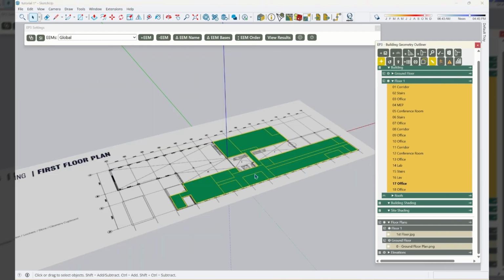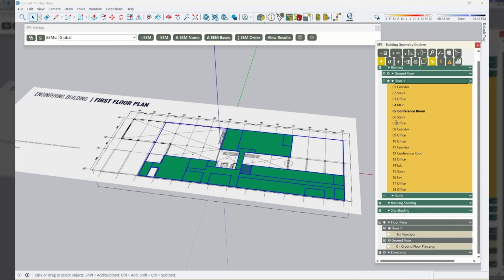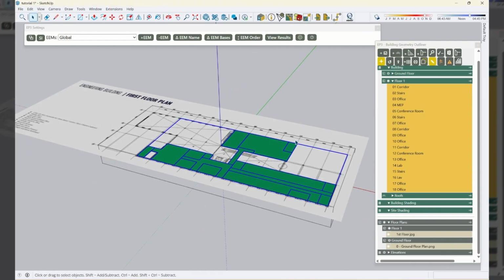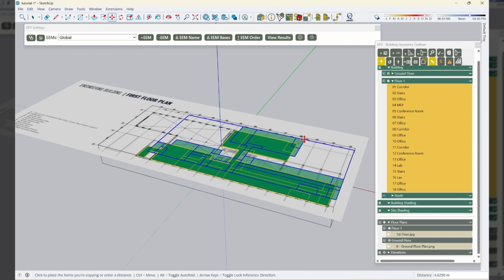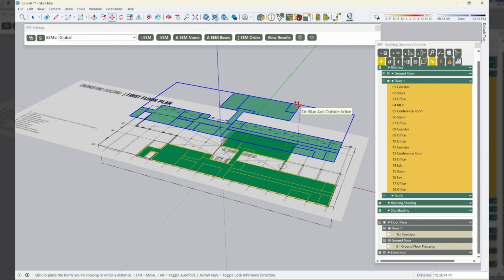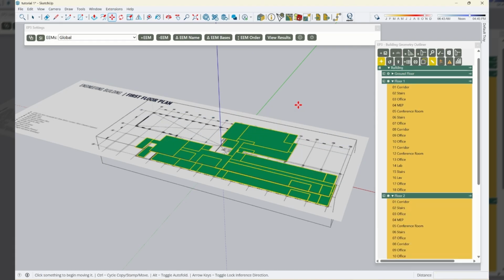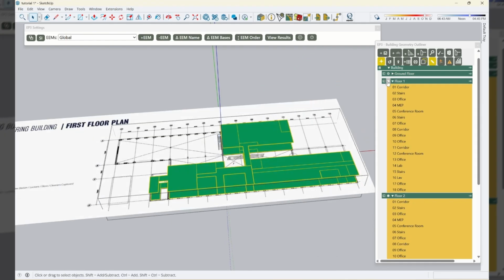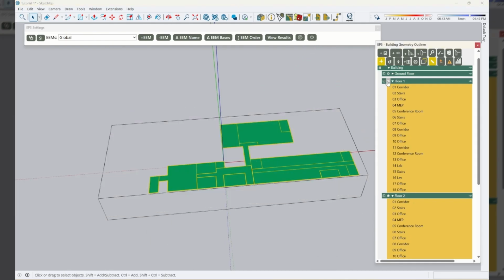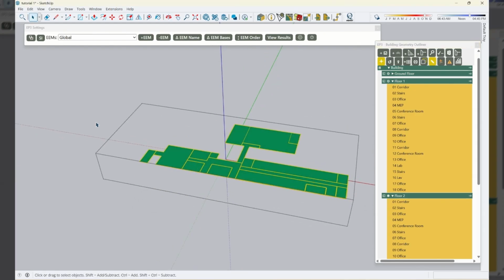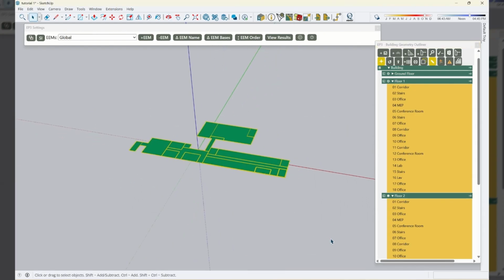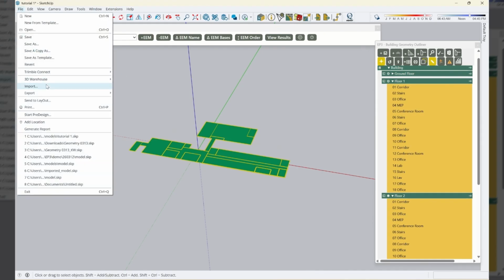So this floor height is a little bit lower. So I'll turn the elevation off. I'll select floor 1, M, grab an endpoint, hit Control. We're going to go straight up and we'll do 3.5 meters. So I'm just typing that in on the keyboard. Okay, so now that's called floor 2. We'll turn off the floor 1 and I'm going to click outside of my dotted line there and I'll say File, Import.